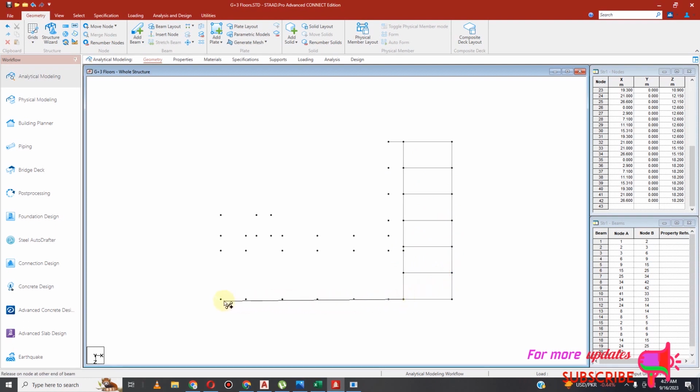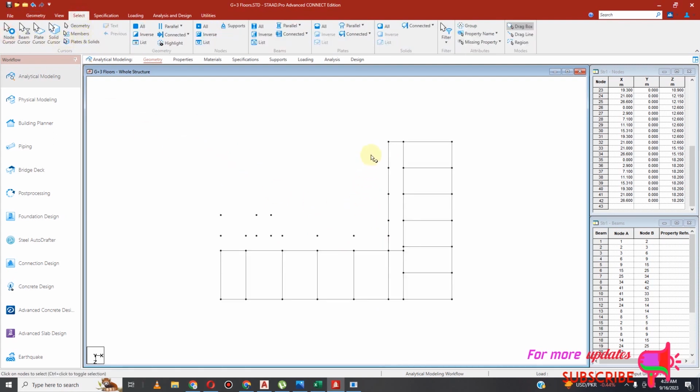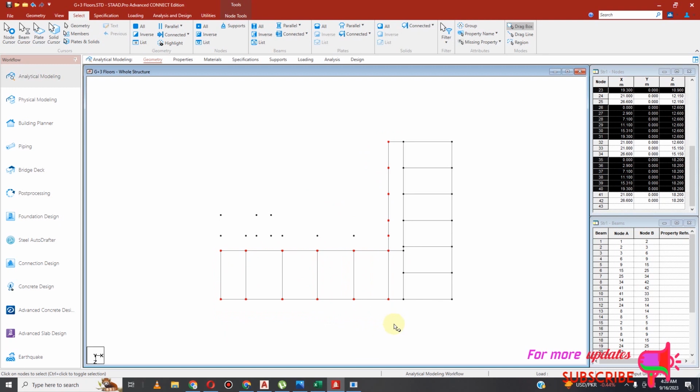So you can just drag up to the end. We're going to deal with that later. We are going to split at those points later, so just from that point to the end. So you just select node cursor, hold control, select again, then split geometry.